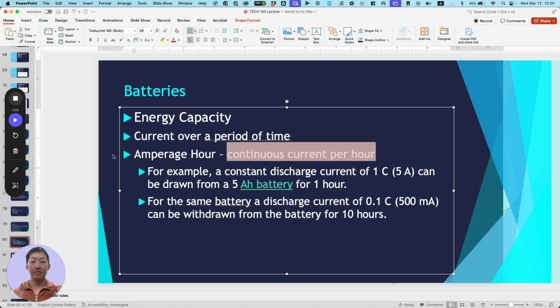So I just have an example here, which is a 1500 milliamp hour battery, just to give you an idea of what type of numbers we might expect. So less than 15 milliohms is new, good, and then over time it builds up, and finally greater than 50 milliohms, it's time to retire.